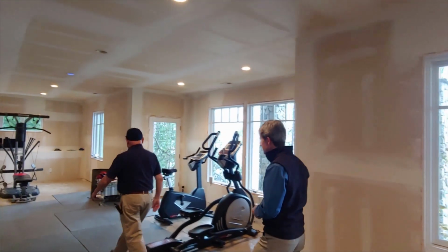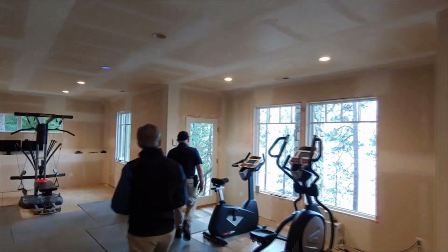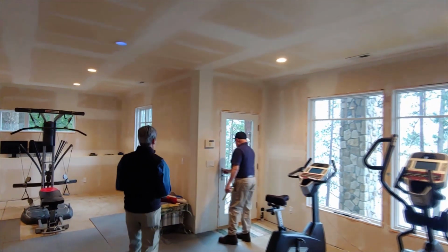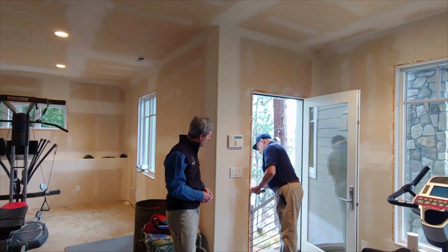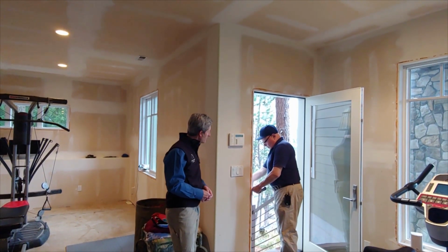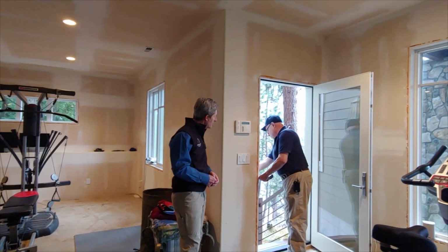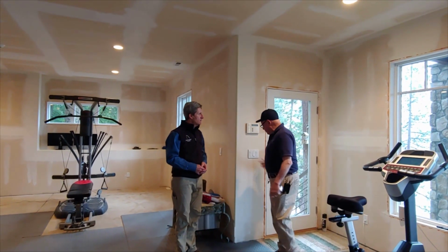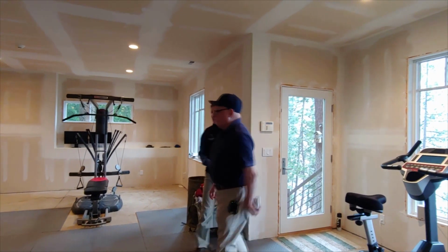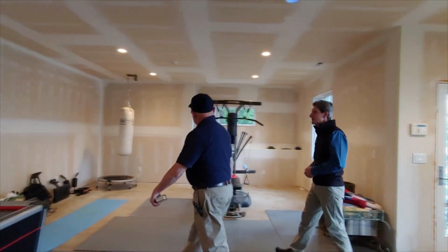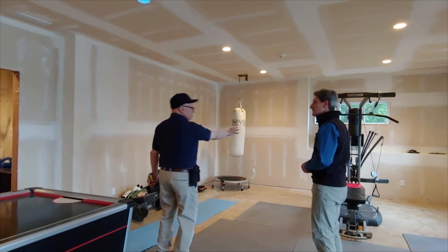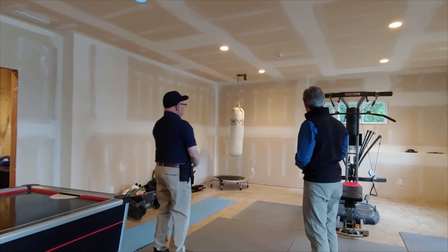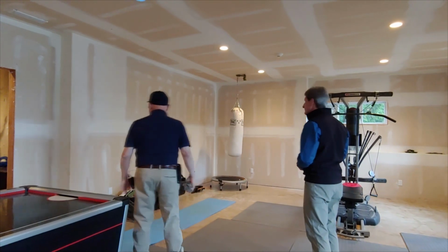I can also confirm that over here with the door. If I open this and measure the jamb, it looks like the total thickness is probably about 6.5. It's exactly what I would expect with a 2x6 wall. That's an easy way to measure, an easy way to look. I'm seeing some issues with the walls over here as far as a cut down. We'll take that into account as well.